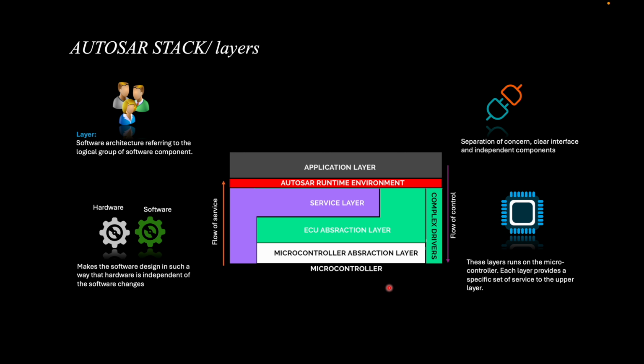How will you solve that problem? To solve that problem, you can use this complex device driver part to integrate non-Autosar compliant software with your Autosar compliant software. So this is a bridge between non-Autosar and Autosar. That is why you need this complex device driver layer.